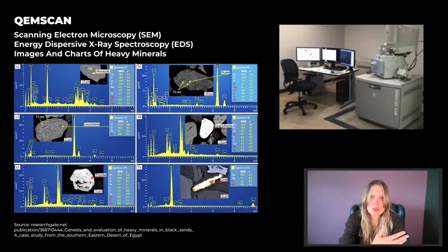Essentially, we take the weight of the dried residue in grams, multiply it by the weight of the resulting concentrate, and then divide it by both the weight of the original sand sample in kilograms and the weight of the portion taken after quartering. Based on the concentrate yield, routine drill hole samples are grouped into composites like barren material, low grade, medium grade, and high grade.